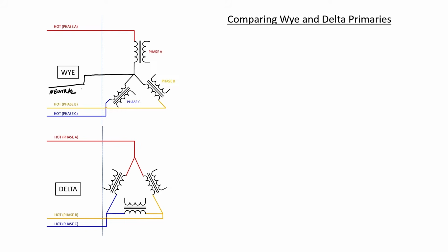You'll quite often see Y-connected transformers near consumer installations. So one residence might be using more power than another residence. You don't want the voltages to fluctuate to these two residences. Therefore, a Y-connected transformer connection would make sense. Let's put some numbers on these transformers.